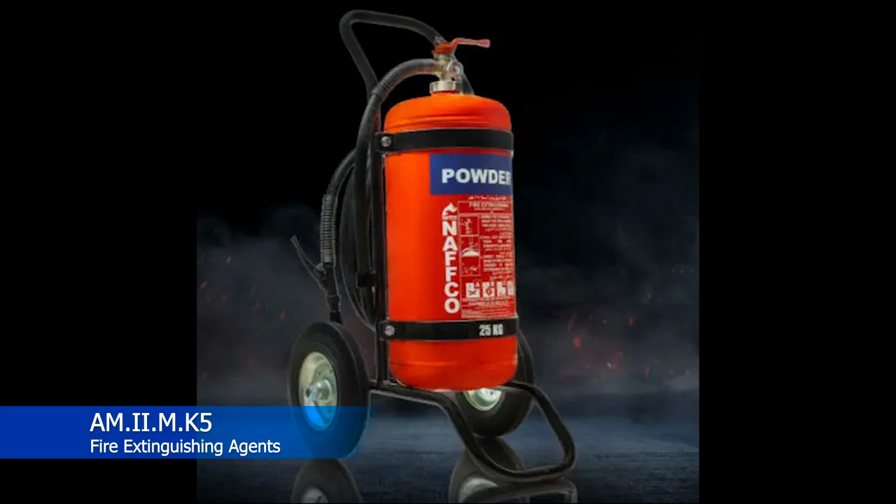Okay, powder is another type of fire extinguisher that you'll see. This is one that you would potentially use, let's say, in the Army, or even at Boeing. We used to launch aircraft, and we'd always have a fire bottle there to help put out anything that might get started. Generally speaking, you don't want to use dry powders, even though you'll still see them out there getting wheeled around, because whenever you spray them, they leave a corrosive residue on the aircraft.